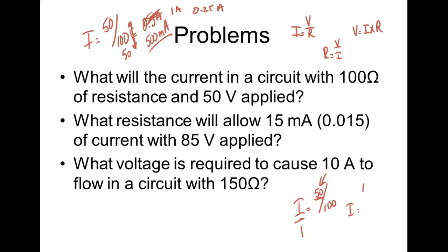Now what directly means is they change in exactly the same ratio, right? So if I come over here and make this 100 volts, and I leave this at 100 ohms, over here my current was 0.5, over here it went up to 1 again. So I doubled my voltage to the circuit, and what happened to the current? The current did what? Doubled. Y'all understand that? This is why voltage is so important.